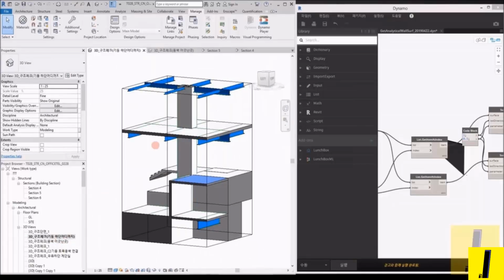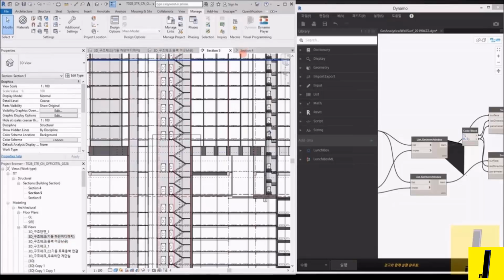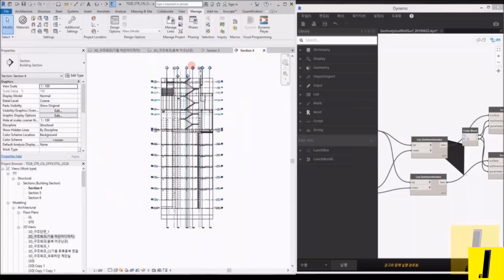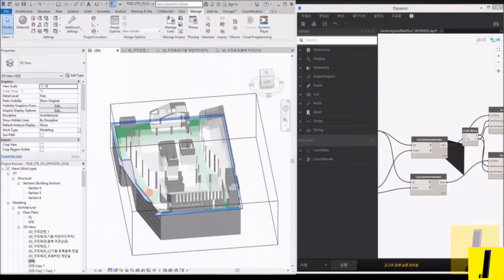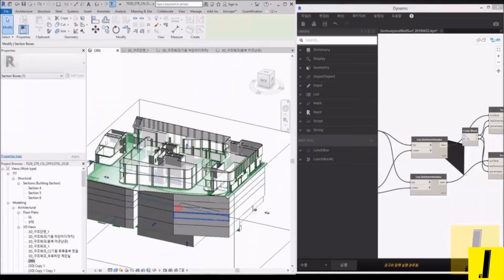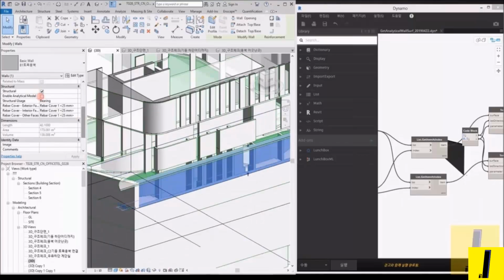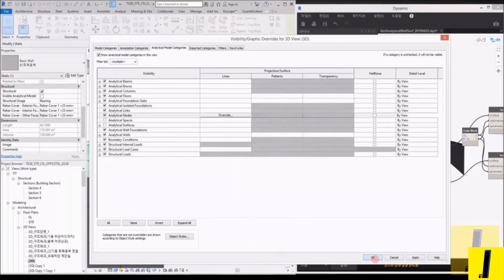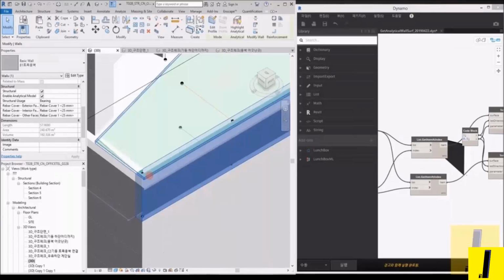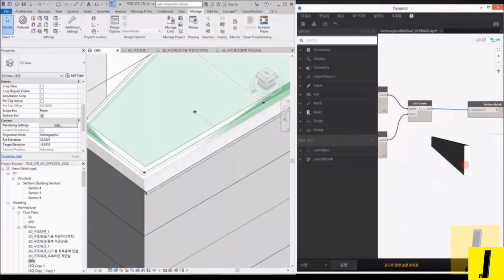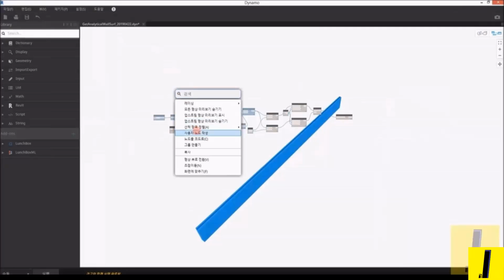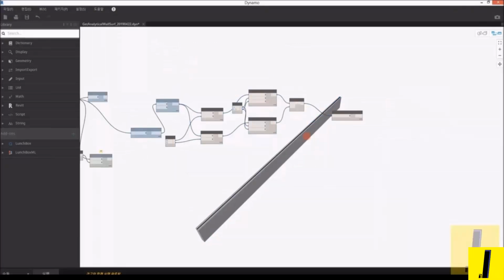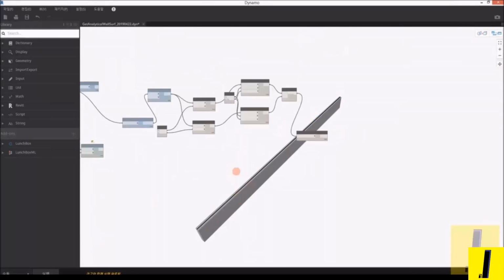And it was quite difficult just using Revit itself, because it has quite many building stories, and amending the analytical model in Revit takes a lot of effort. So I decided, okay, let's organize the model to use in the Rhino interface with SOFiSTiK, so I can simplify the structural framing, walls and floors using Dynamo. And Dynamo is a kind of visual scripting interface for Revit.